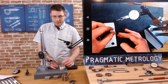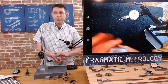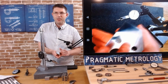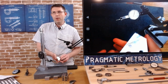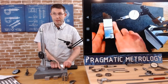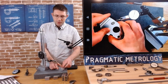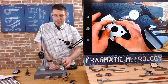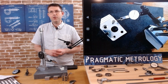Datum A may not be perfectly perpendicular to these faces, which is where things get a little complicated. You're making that assumption, so you could verify that. You could go down a rabbit hole, but if you checked it this way and there was a difference, and you check it this way and there's a difference, and you check it this way, this will probably be the best way to do it. Check this way, and you'll just add this to your two-dimensional position error.